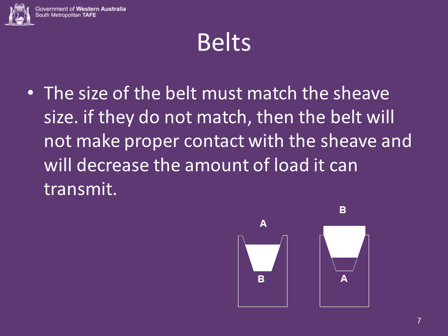Power band belts. These use the same top width designation as the above belts, but the number of ribs, or bands, is designated by the number preceding the top width designation. For example, a 3-ribbed 5V belt will be labelled 3/5V. Positive drive belts XL, L, H, XH and XXH.